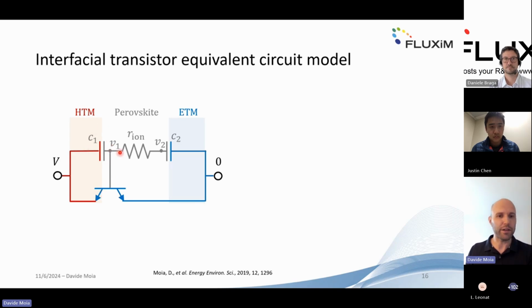So what we have here is the very simple ionic branch that I showed in the beginning of my presentation. And assuming that ions are essentially establishing the changes in electrostatic potential in the device, we can then use a single transistor to implement this ionic to electronic current amplification, which is essentially saying if we have a variation in potential due to ion motion, we will have an out of phase change in current due to this electronic recombination that will change with the electrostatic potential.